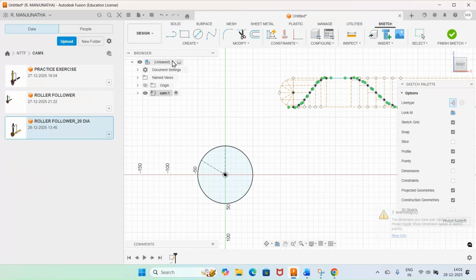Okay. Then go to line and draw one more inclined line. Go to line, select this line and draw this. Then go to dimension between these two. So what is the angle, which is 45 degree? Select this. And again, you go to trim this portion. Again, from here, you draw one more line of any angle. Then go to dimension between these two. What is the dimension? It should be 90 degree. So type 90. Then you go for a trim. The rest of the things will be 135 degree, 165 degrees. So go to dimension between these two. So you're going to get it as 165 degrees.